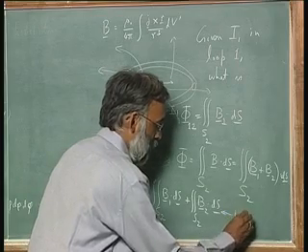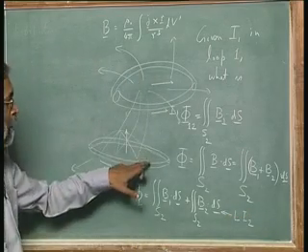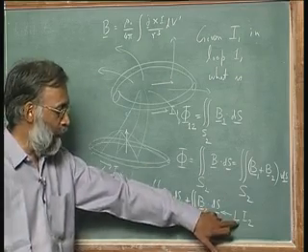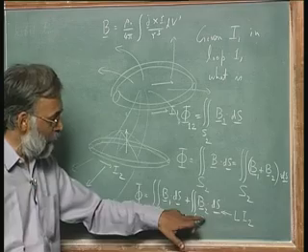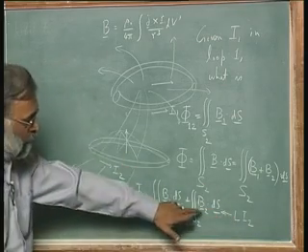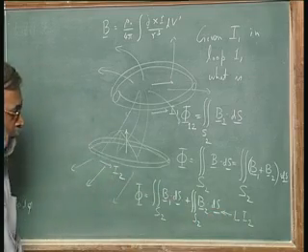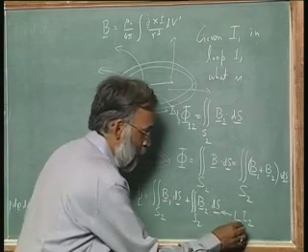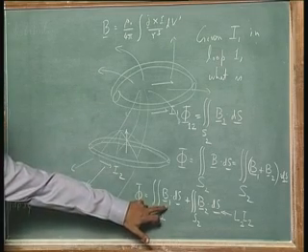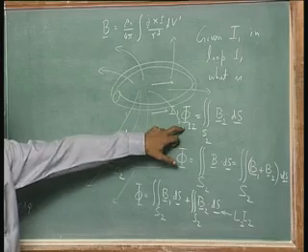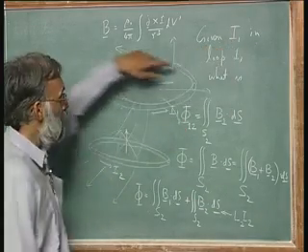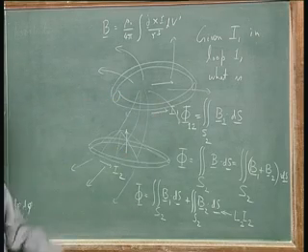Li, because if you have a current in a loop and it generates a magnetic field, the inductance of that loop is nothing but this flux divided by the current in that loop I2. So, this flux is L times I2, and because it is coil 2, I will put it as L2. This flux, however, is a new flux, it is this phi 1 2, and it is not due to I2 at all, it is due to I1.